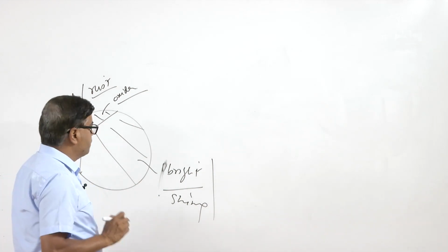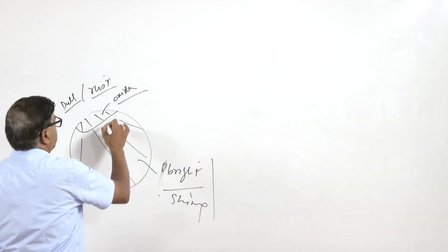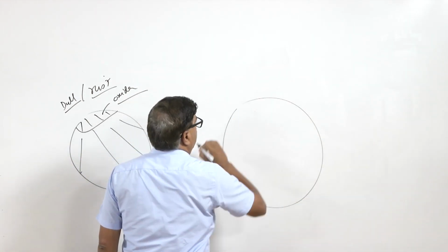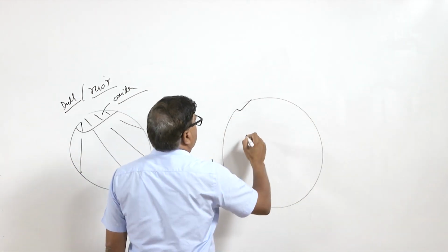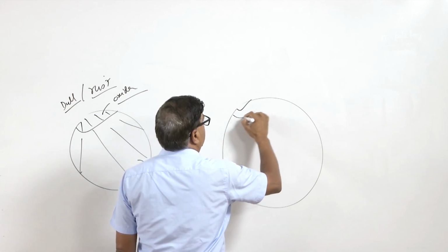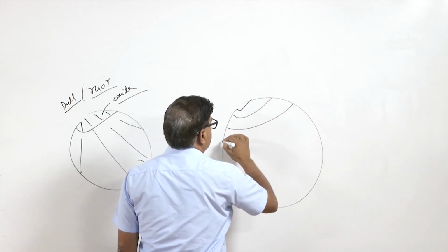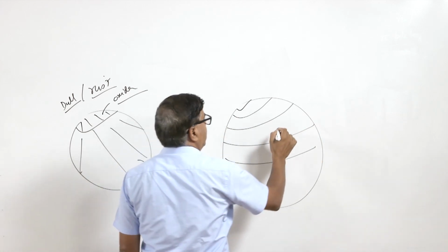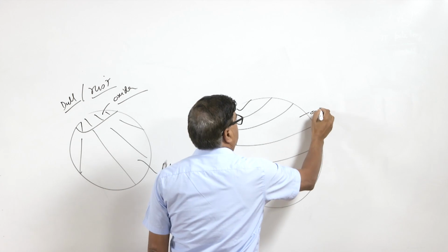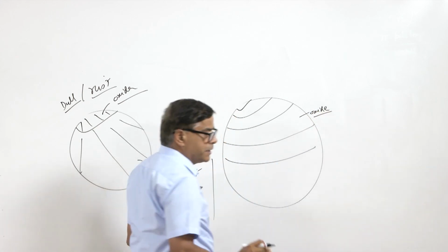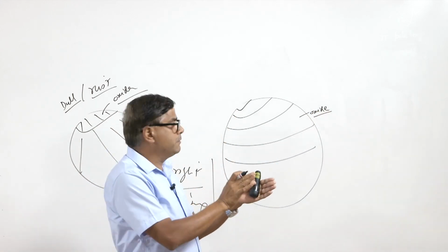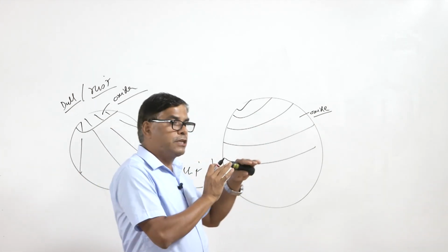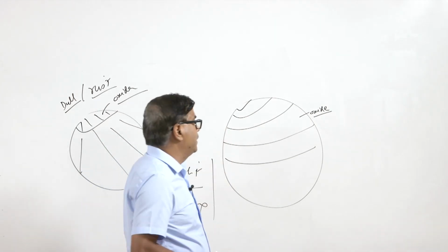There is one more aspect: if this is the crack which has nucleated and then it is growing slowly like this, then by measuring the oxide thickness layer and using the oxidation kinetics of that material, we can estimate for how long this surface was exposed to the environmental conditions.